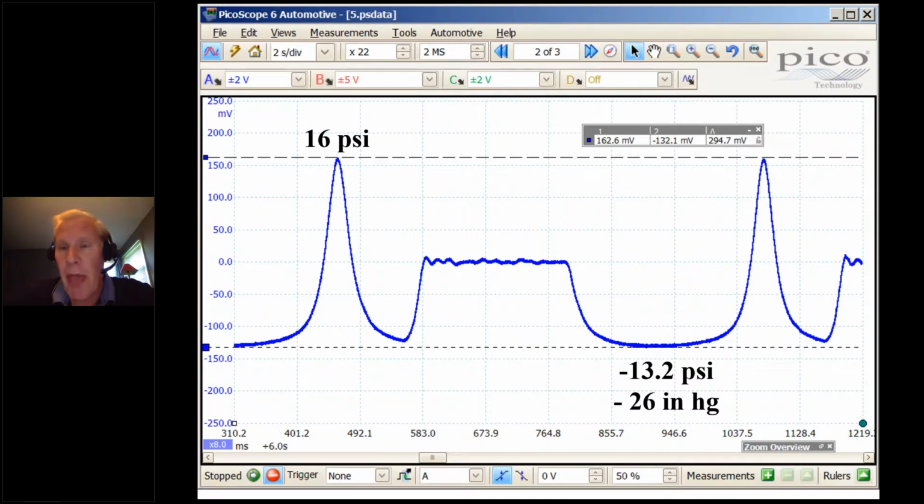Do you think I could pull that kind of vacuum with a hole in the piston or a chunk of the exhaust valve? This cylinder doesn't have a leak. I have a symmetrical compression tower. Yeah, it's really low compression. And I have EVO, I have an exhaust valve event. I don't think I have an intake event. This is very, very rounded. There's a lot of time spent in a vacuum. You've heard that term before.